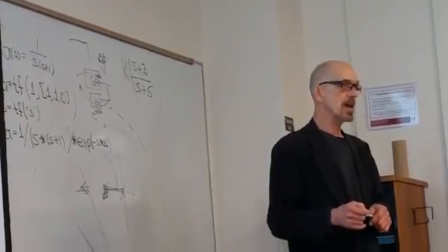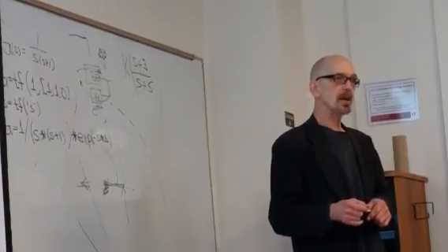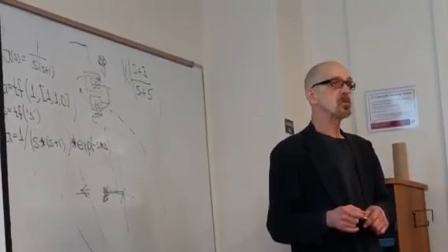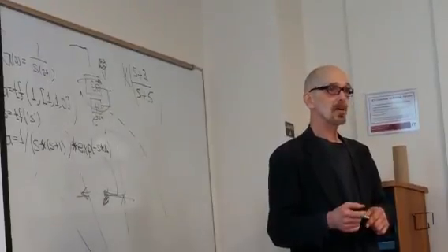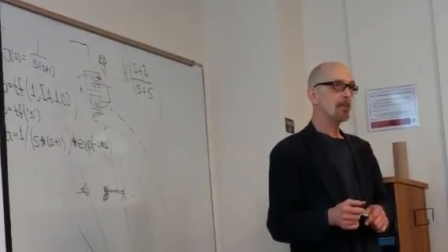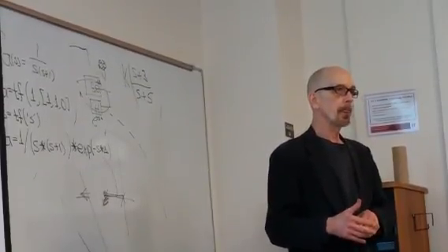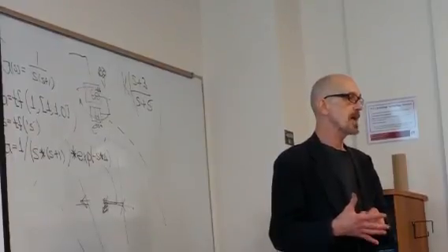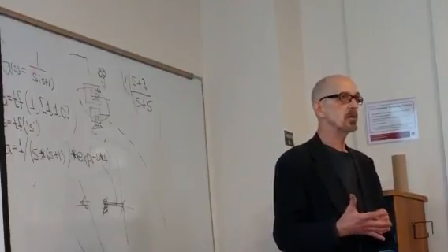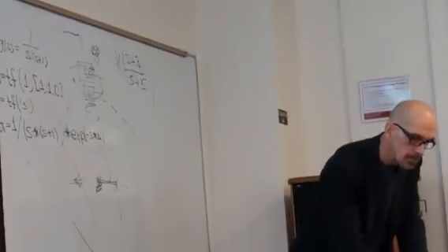This is the root locus magnitude and angle criteria. So in your frequency domain, it becomes 0 dB at the same frequency that your phase is -180. If that happens at one frequency, that frequency is a closed loop pole. And it's not just any old closed loop pole, it's a pole on the imaginary axis, which means your system is marginally stable.